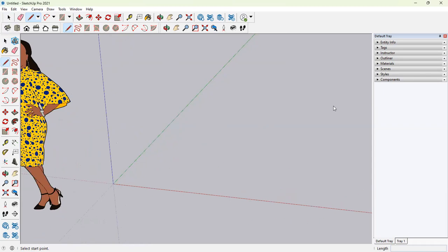Now, if you noticed, on the left-hand side of your screen, it will show you the command line. This is similar to AutoCAD, how it shows you the directions that you have to go. It's saying select a point. So let's say I've selected a point and I leave my mouse. Do not select and drag, because this will just create a solid line. You always have to click and leave so that your line tool is activated, but it's not snapped to any axis.